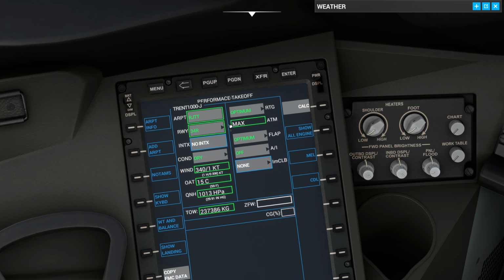We want it to do the maximum derate possible using the temperature, using us telling the airplane it's hotter than it is. But above that, we also have a rating. So on the 787, we can actually derate the engines with a fixed derate. That means we can tell the engines, not only are we going to use a higher temperature, we're also going to say to them, no, you're also only allowed to use 80% of your power, or 90% of your power, or 100%. So that's what we have here. Full takeoff thrust, derated by 10%, and takeoff thrust derated by 20%. And then on top of that, we'll have the temperature as well.